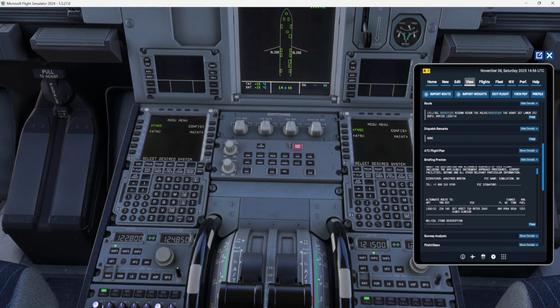Okay, we go to the MCDU, we go to ATSU, and we select the AOC menu. Free text we have here. Let's read together, my friend. We have a zero fuel weight of 57.4. We don't take takeoff weight into consideration. The maximum, where is it?